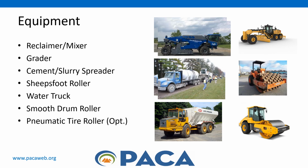There is no doubt that various pieces of equipment are required for the placement of cement soil stabilization. They consist largely of common roadway construction machinery, though the reclaimer or mixer is needed to uniformly mix the cement into the native soil. The following equipment is recommended: reclaimer or mixer, grader, cement or slurry spreader, sheep's foot roller, water tank for dust control, smooth drum roller, and a pneumatic tire roller is optional.